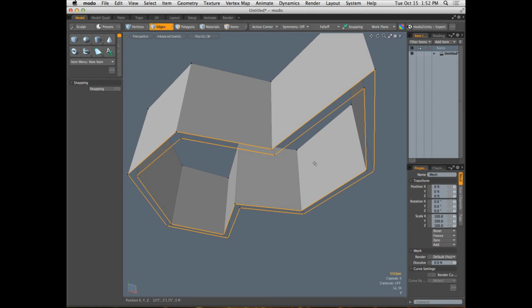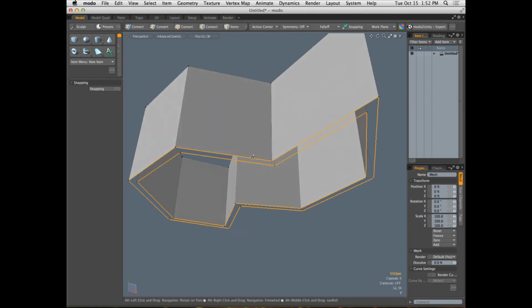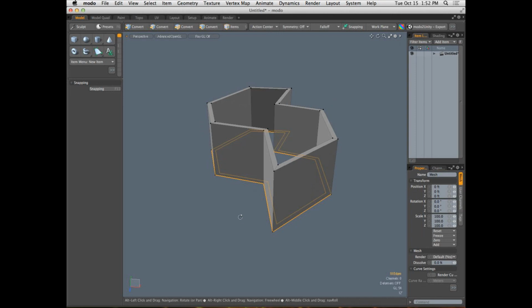So it's kind of wasted space to a certain degree. It's polygons that we're never ever going to see. However, it would be nice to have polygons over there because the loop slice tool works better when there's a loop of polygons around every single part of this object, okay? So I like to have polygons down there while I'm modeling, and then usually 9 times out of 10, there's not enough down there to really worry about. So you can delete them, you can keep them there.